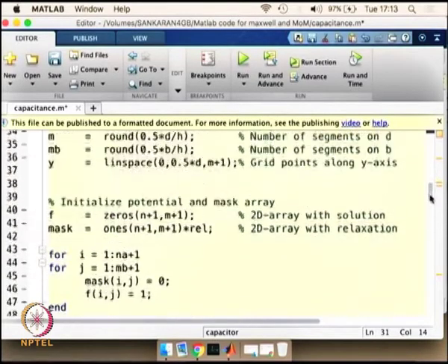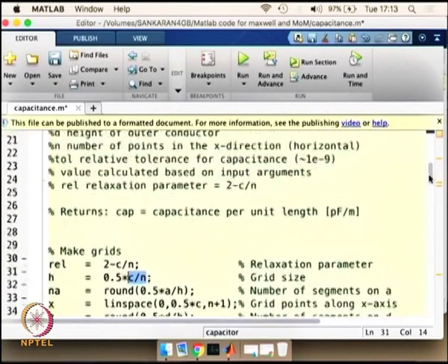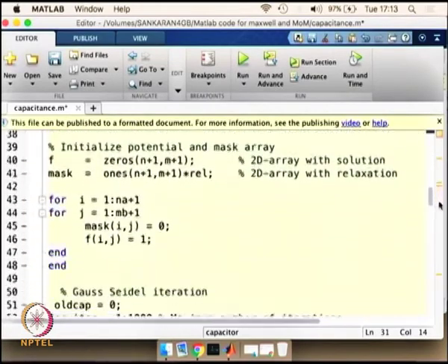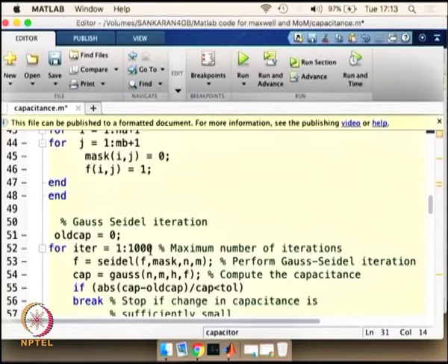One of the things that we have to give here is also the number of iterations, and for a problem of this type we set the iteration to be 1000. Of course we can change the iteration to 10 or 100, but it is going to affect the convergence of the result. So we keep 1000 as a nominal value here. Obviously you can change that and find out what is good for your particular case.